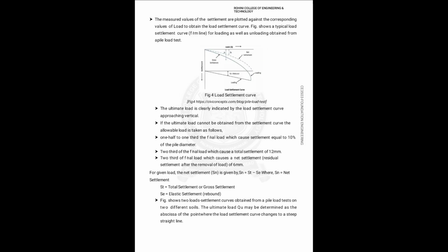20 and 60 minutes. The test pile is loaded until the ultimate load is reached. The test load is increased to a value 2.5 times the estimated allowable load, or until failure occurs, whichever is earlier. The load is removed in the same decrements at 1 hour intervals, and the final rebound is recorded 24 hours after the entire load has been removed.